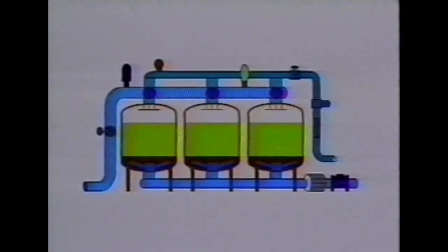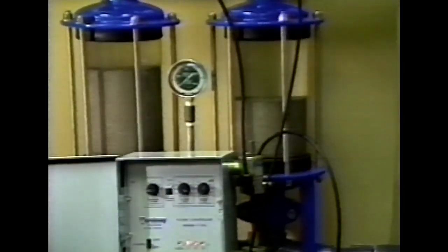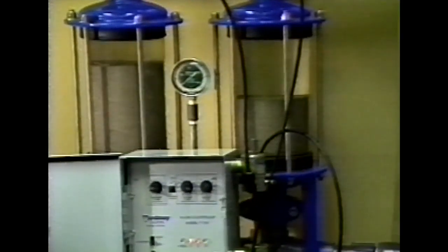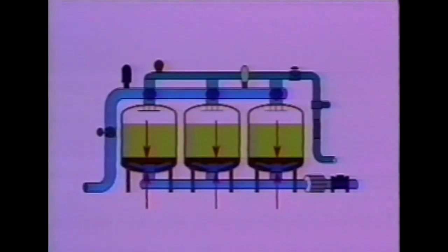Each media tank is filled with sand-sized particles. This media, usually crushed granite or silica, provides the filtration and has a bed depth of about 14 inches. Tanks are flushed frequently enough so that the majority of the debris is captured within the top 4 inches of the media bed. An underdrain is at the bottom of each tank.